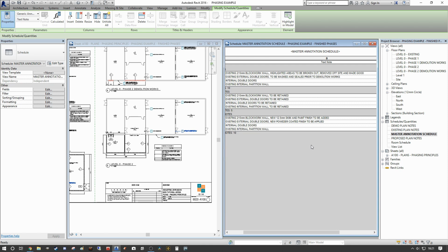So that is a very, very Revit-y way, I suppose, of controlling your generic annotation and text notes within Revit. It has a very low barrier to entry. You don't need to be a family whiz or a parameter creation wizard. You don't really need to know a lot about family generation in terms of model geometry, doors and windows and that kind of thing, to be able to effectively schedule your whole project and really control the full spectrum of annotation across the project with ease.